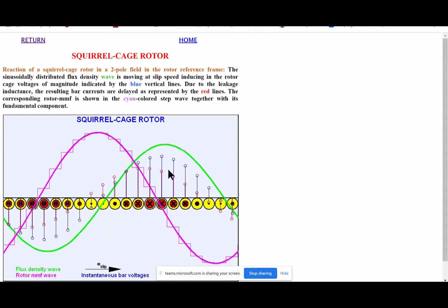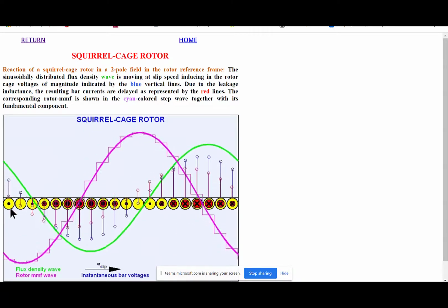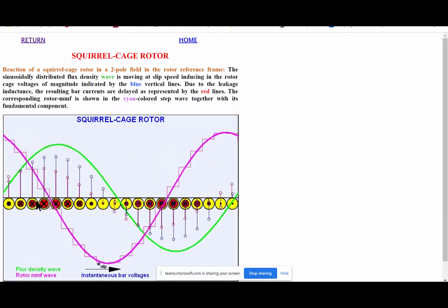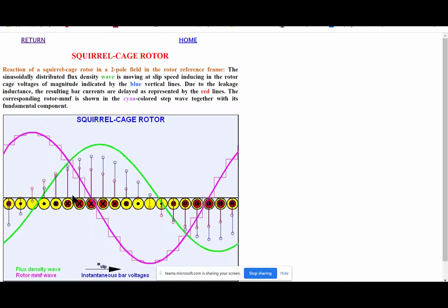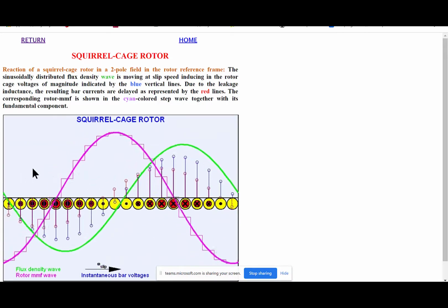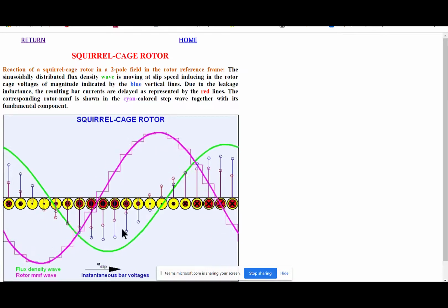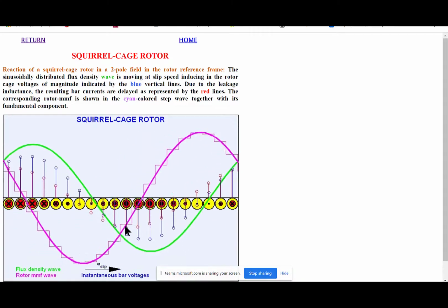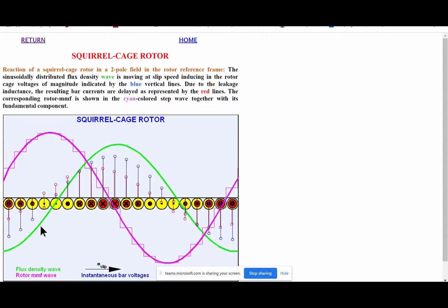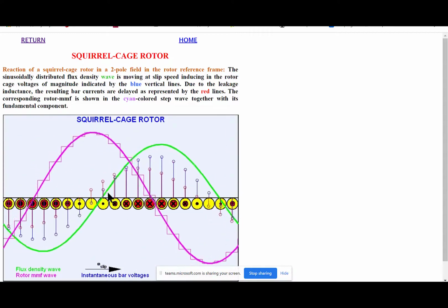But essentially what's happening is you're running the MMF through the field, and you just have these conductors. You don't care whether they're A, B, C, or D, but it effectively impresses another rotating MMF, which mimics three-phase, onto these rotors. So that's the magenta here, caused by the flux.